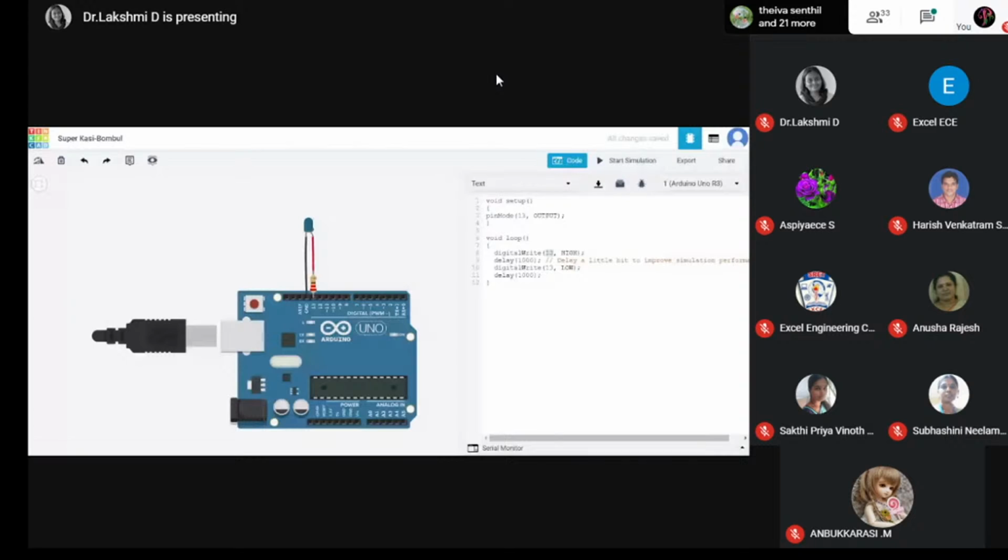Nothing more. If you have that practice comfort, that's more than enough. See, the other program I'm showing: look here, I made a connection to pin 9, and it is working. Pin 13 is dedicated to the LED on the Arduino. The same code, the only change I made is the pin number. Digital write is a portion related to digital pins. This is a portion related to analog pins. Potentiometer is one example for analog, so I have brought one analog example.